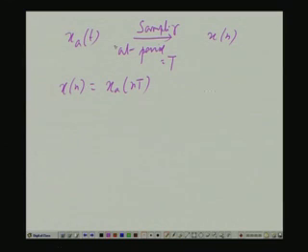So, one sample is taken at t equal to 0, another at capital T, then 2 T, 3 T, 4 T. So, the nth sample x n is the value of this function x a t at what time point? At n into capital T. Fine. So, what is R x x k? Whenever I write R x x k, look at what I write inside. If it is k, and k stands for an integer, then I am talking of the correlation function of the random sequence. If I write R x x tau, then I am talking of the autocorrelation function of a continuous valued, that is analog, function, because tau is continuous. Now, what is R x x k?